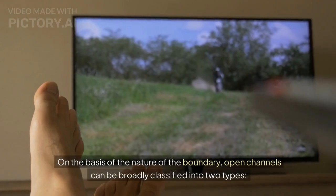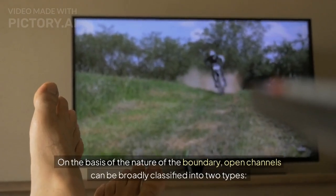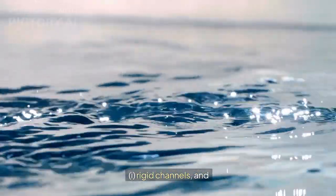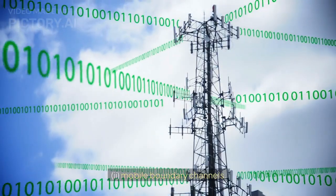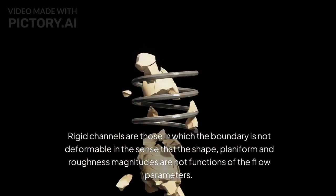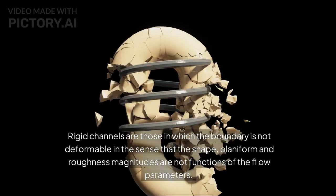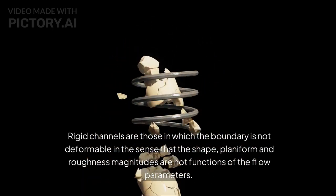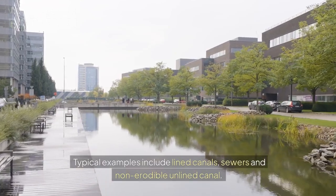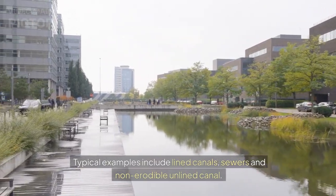On the basis of the nature of the boundary, open channels can be broadly classified into two types: I, rigid channels, and II, mobile boundary channels. Rigid channels are those in which the boundary is not deformable, in the sense that the shape, planform, and roughness magnitudes are not functions of the flow parameters. Typical examples include lined canals, sewers, and non-erodible unlined canals.